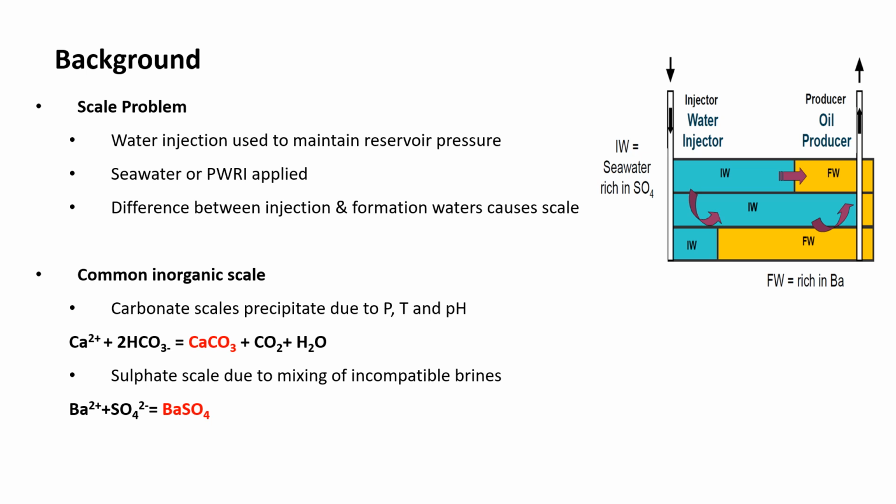Background: what is the meaning of a scale problem? It is a very common problem when oil fields use water injection to maintain reservoir pressure, or even when seawater or produced water re-injection is applied. The difference between injection and formation water causes the scale problem.